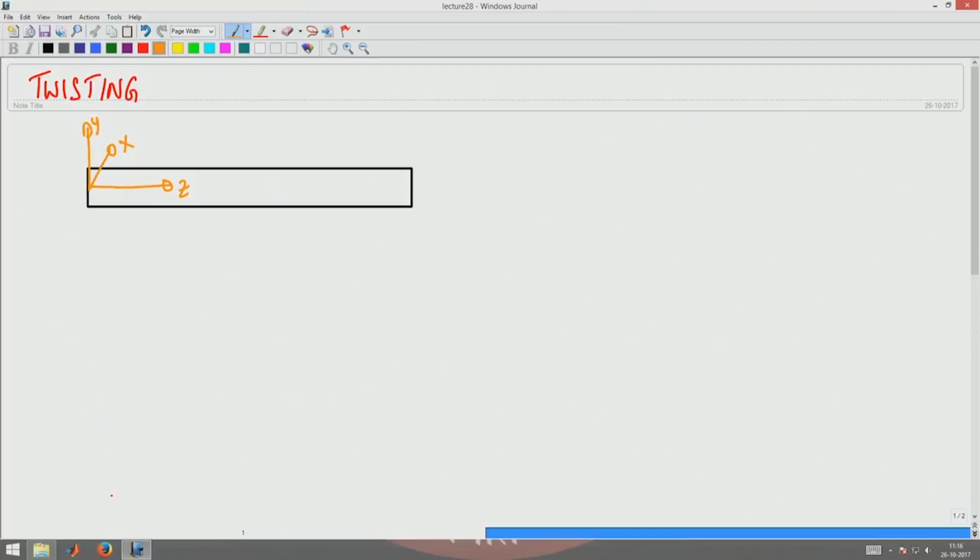So as I did before for the bending moment, I cut a section, expose the traction along the Z direction, and find what is the torsional moment. Now T of e_z, I am not going to go into the step by step procedure. You have to refer back to our first lecture in beam bending where we did this with respect to X to get these expressions. T of e_z will be given by sigma_xz e_x plus sigma_yz e_y plus sigma_zz e_z.